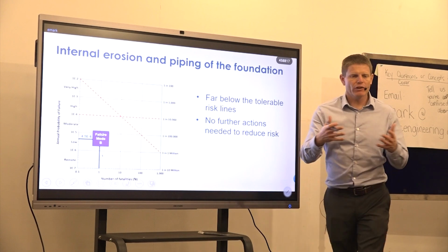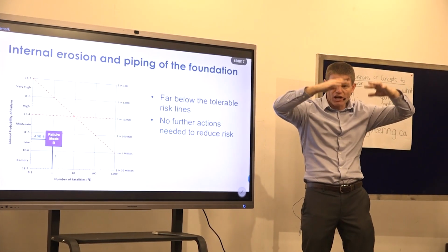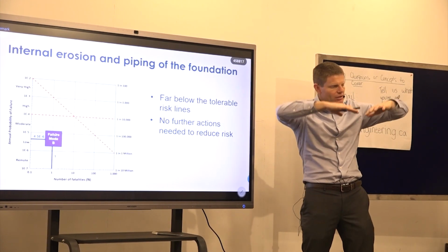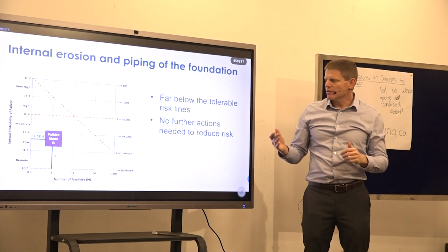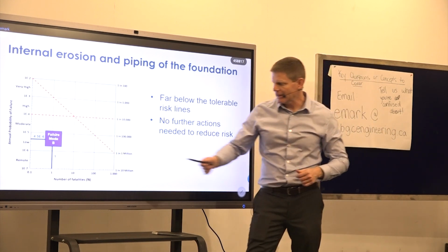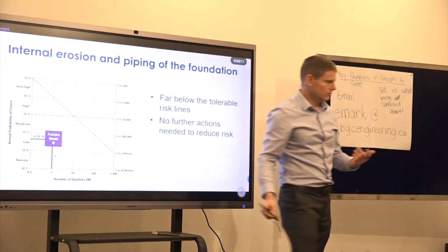And even if that failure mode occurs, remember the top of the barrier only settles a small amount because it's concrete, right? So it doesn't disappear like an earth dam. It only settles a few meters. So then when the debris flow passes out, it's actually a very small debris flow. So in that case, it doesn't kill very many people. So that failure mode would plot here, right?